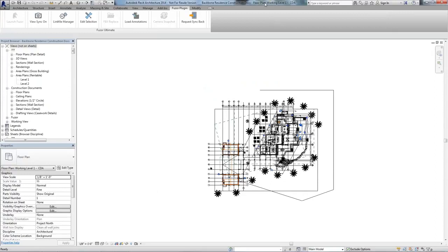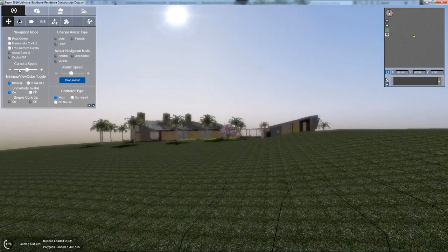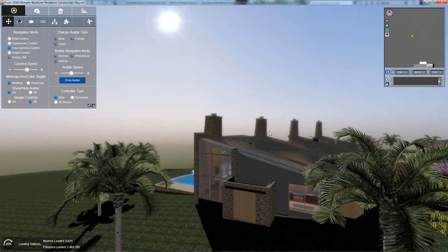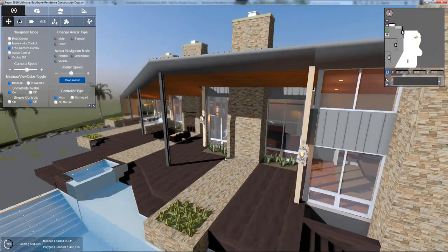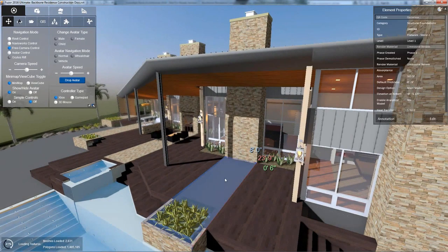That's all very functional, because the annotation file you save out of Fuzor can be loaded back into Fuzor but also into your authoring software, and it can serve much the same function. So let's go ahead and duck over here to free camera while it's trying to load the rest of those. Let's click this and make an annotation really quickly.